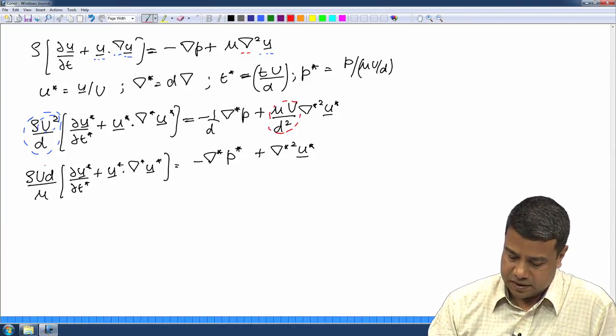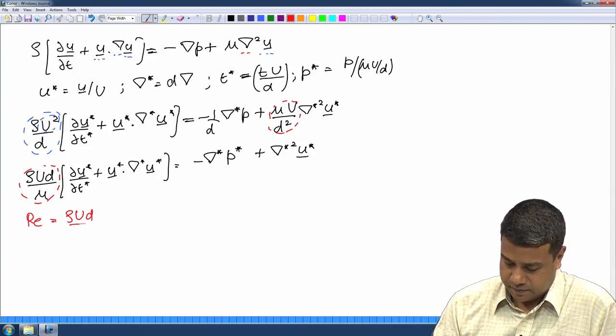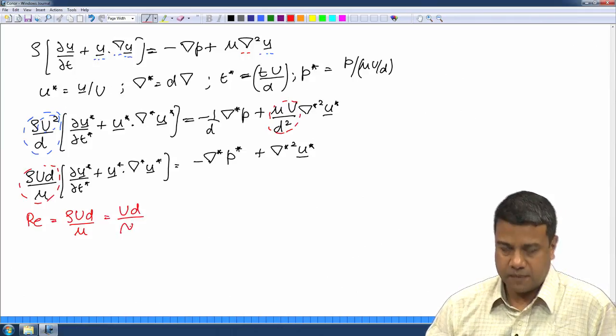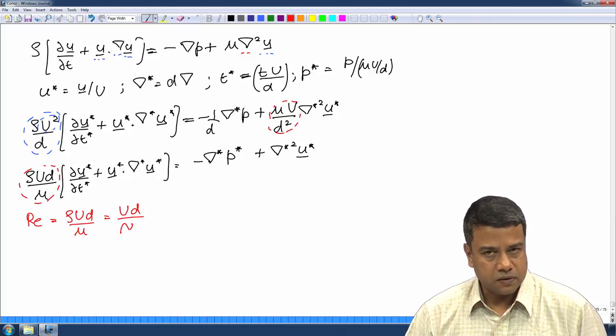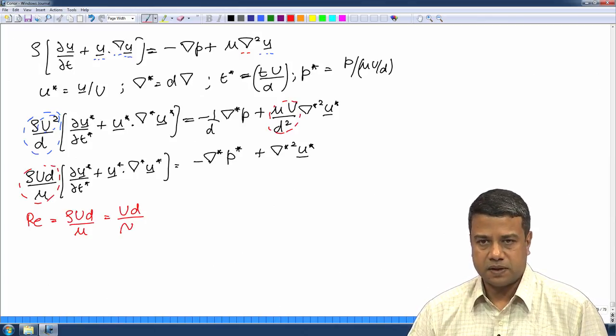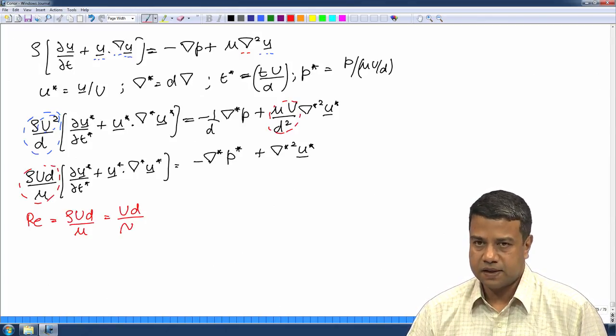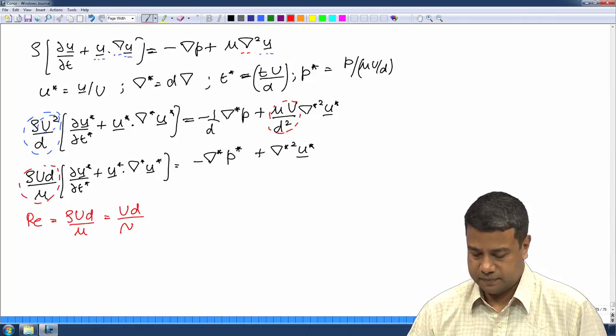And on the left side we have the dimensionless number, the Reynolds number, divided by the kinematic viscosity or the momentum diffusivity. Okay. So, all of these equations have a common structure. On the left side you have the Peclet number or the Reynolds number times the time derivative and the convective terms. On the right side you have the diffusive term.